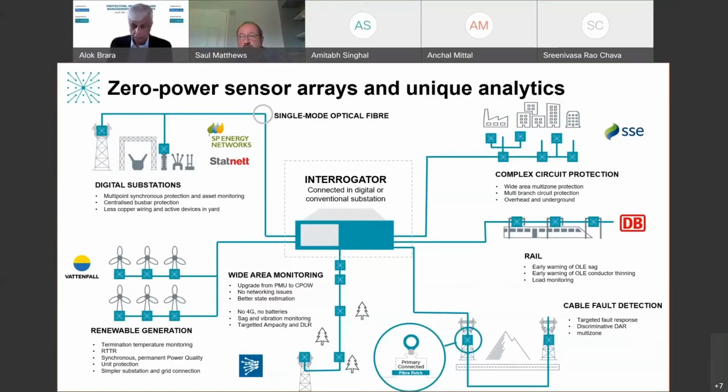So this is upgrading from distance protection on traditional circuits to a line differential protection scheme or a unit protection scheme where you've got multiple branches created by new grid connections, and those new grid connections typically are new wind farms plugging into the network, and that makes a dramatic difference again to the cost of the system, where you're able to provide superior faulted section identification using unit protection so that you know which branch contains faults, and then you can respond to a fault in a more appropriate and granular and safe manner.